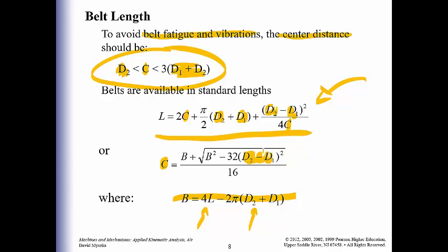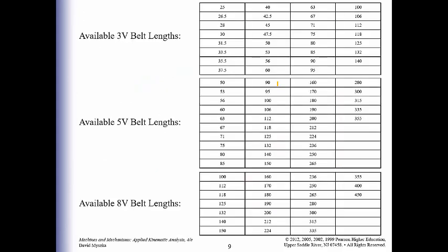But these would be how you would get the standard lengths of your belts. Available 3V belt lengths, 5V belt lengths, and 8V belt lengths are given in these tables right here, and these would also always be in inches as well.